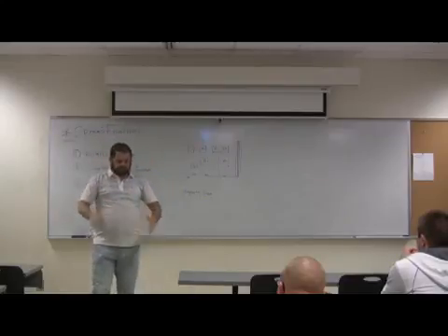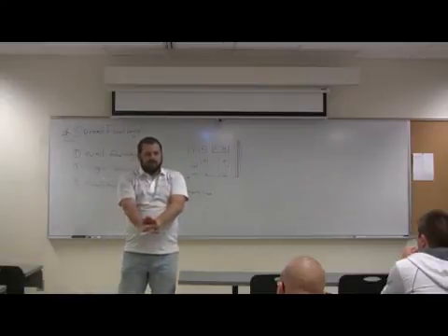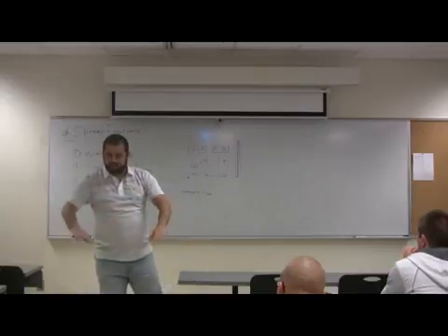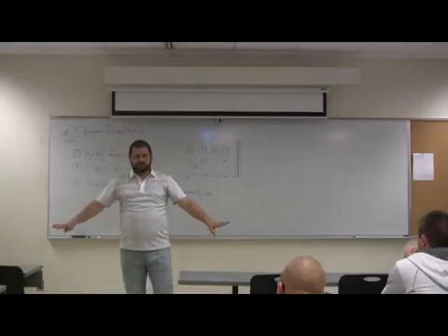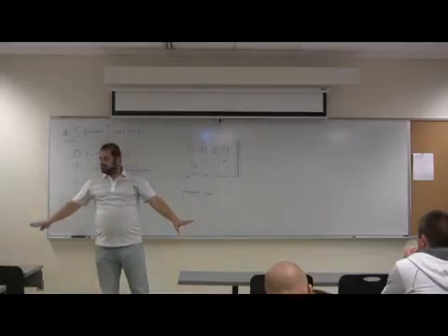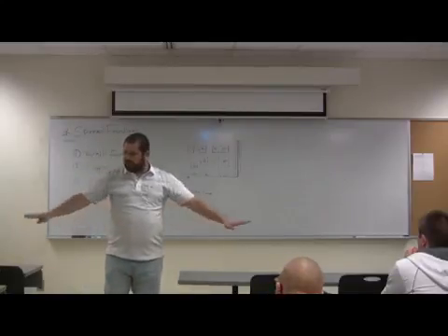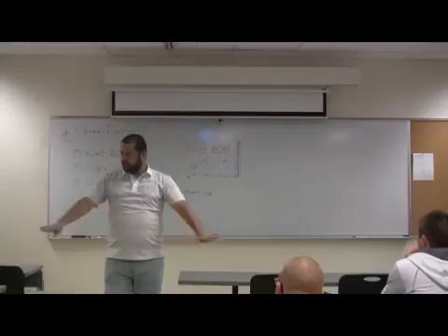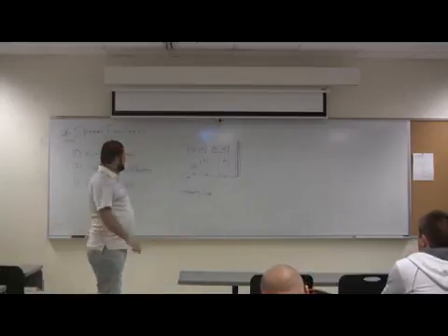Okay, so usually once you come to the level, you level your surface, that's the level of the first floor, the entrance, there's a slab on grade of about 4-inch. And the reinforcement there is usually the minimum for shrinkage and temperature. That's just for connecting the columns at the foundation level.